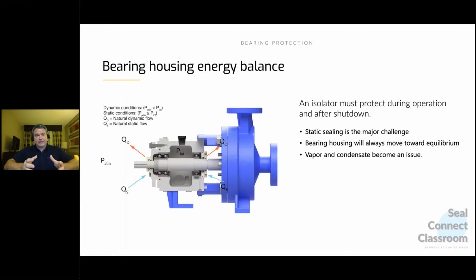As the hot machine is running, it's venting out. This is a great place to talk about that. When the machine's running, it's venting out, and you have heat and higher pressure inside of the machine. The air is traveling out through your vents, through your breathers, through your seals. When the machine is shut down, the power is off, the machine begins to cool, and everything reverses. Everything is now coming in through the breather, in through the seals.